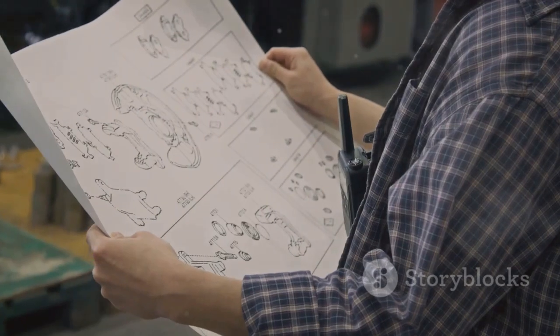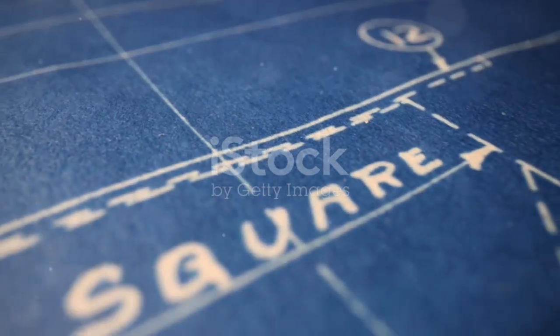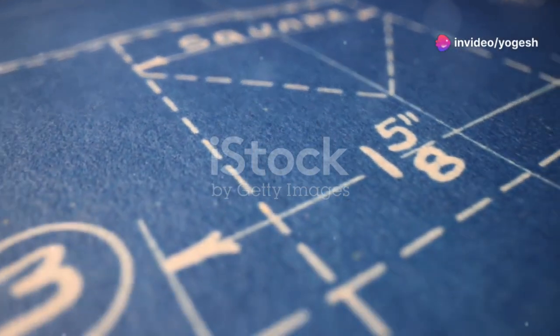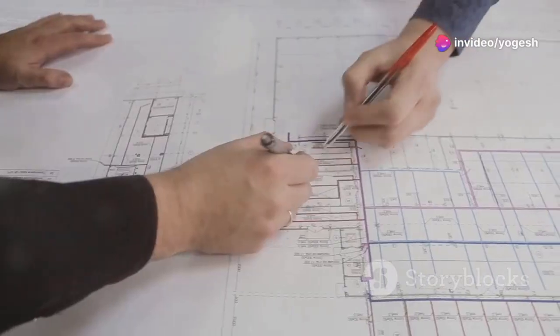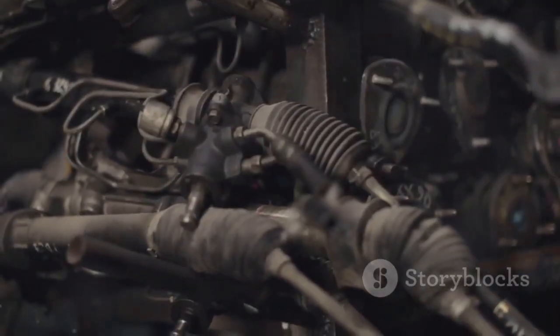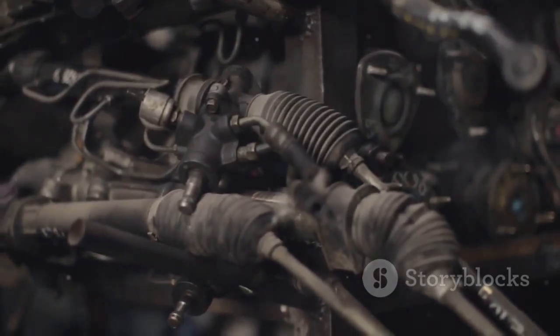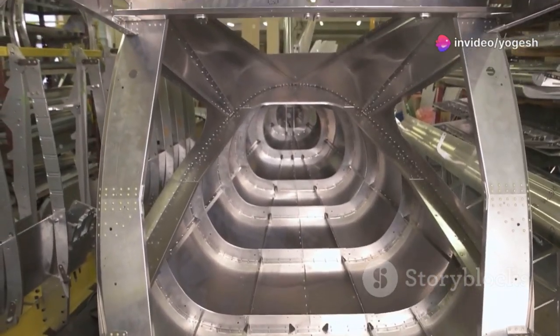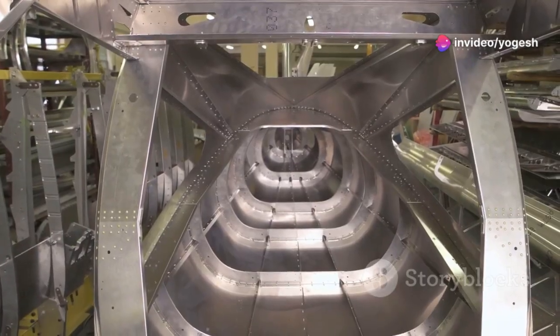Sectional views have rules for clarity. Hatch lines are thin, black, and uniformly spaced, usually at 45 degrees. Consistency and clarity are key. In assemblies, change hatch angles for adjacent parts. This distinguishes components visually. Don't hatch standard parts like bolts or ribs parallel to the cutting plane.